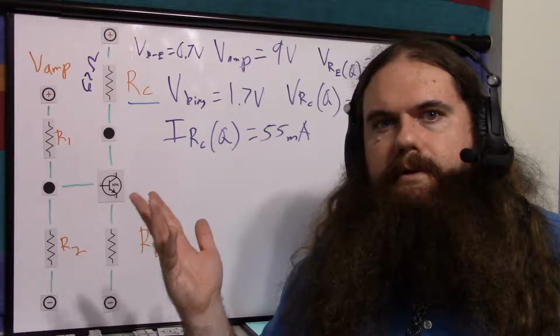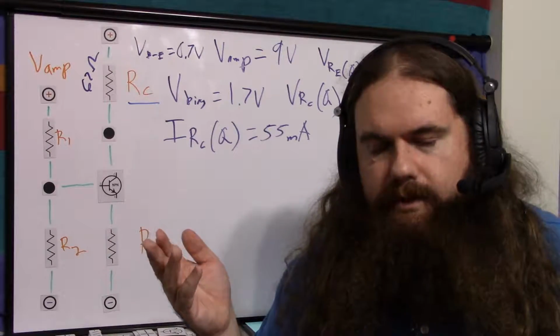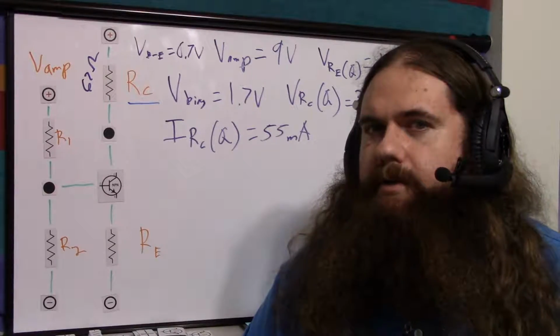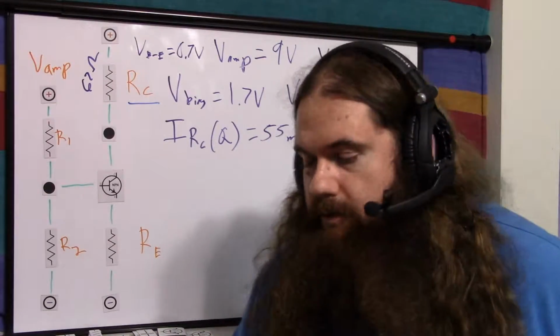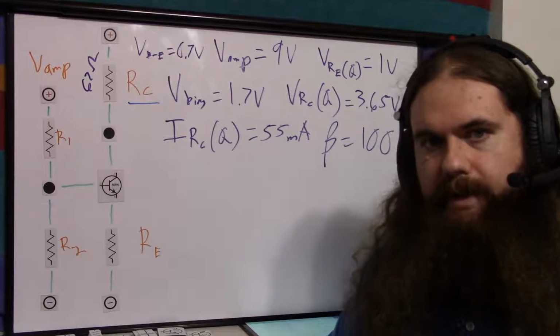But this just shows, if you go on the internet, you'll usually see 100. Like, pick beta is 100. 9 times out of 10, they're going to be approximating beta with 100. So I recommend you just don't worry about it too much and do that, unless you have a weird transistor. So we're going to pick beta equals 100. So this is the approximation we'll use.